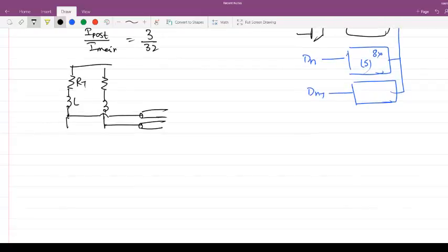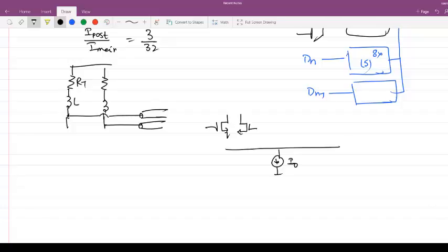I am always having the same fixed current source, let's say I naught, and I am having different input pairs. How are you going to connect these input pairs, which can be controlled by Dn or Dn minus 1, to this current without splitting I naught? Question is that, right?